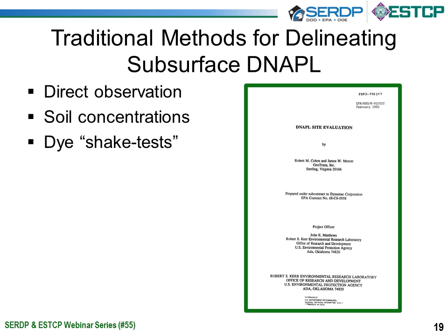Soil concentrations are another recommended method where you use a direct push technology or other drilling tool to collect soil samples and then send the samples or a sub-sample off to a laboratory and analyze for your constituents of concern. And if the total concentration is above a partitioning threshold, you likely have a DNAPL or separate phase NAPL present.